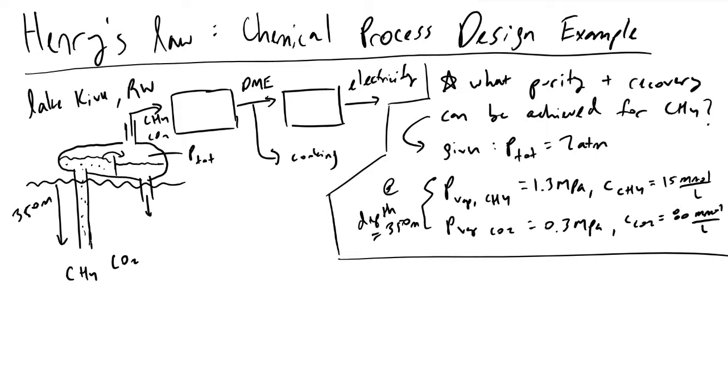At these depths, if we plot charts like these, we'll have the hydrostatic pressure on the x-axis, and the partial pressure of some component i on the y-axis. This is the hydrostatic pressure, which will be proportional to rho g h, and then it will also have certain vapor pressures for various components i, like here.